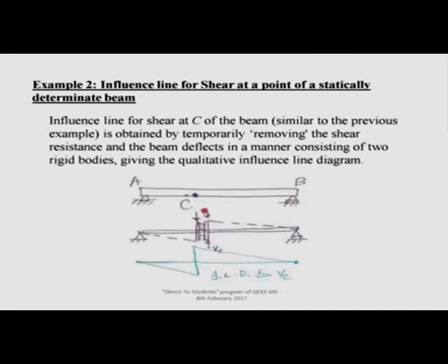Definitely this shear force is making this part go down. That is why, to me, this BC, which is the shear force V at C, is positive according to my idea. Next, this V is also pushing the left part up according to my sign convention: left up and right down. Left for this portion and right for this portion is actually a positive sign convention for me.